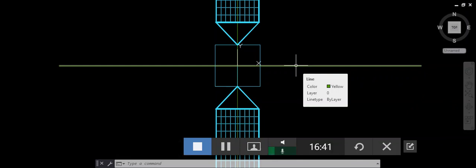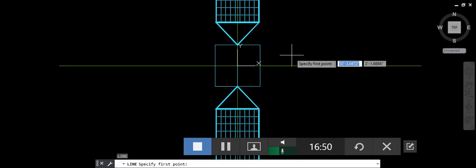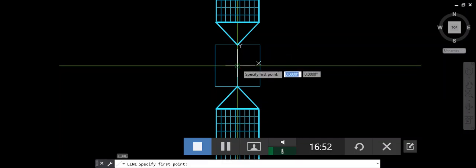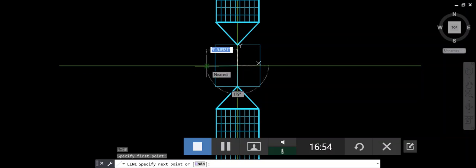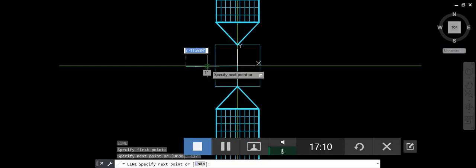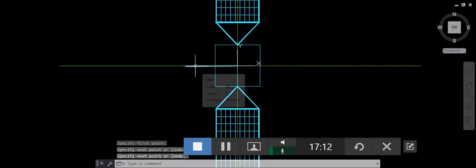We need another circle, okay, for the antenna, and we need to locate that particular circle at the end of the line. So we need a construction line. Line, enter, okay, from the center point to the left, and we are going to the left how far? 234 divided by 2, so 117 to the left. So 117 inches to the left. Okay, this is your center point.